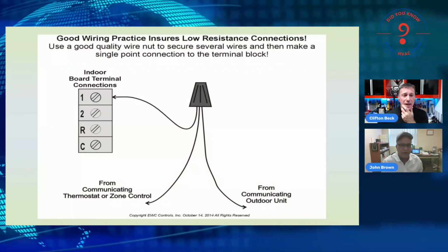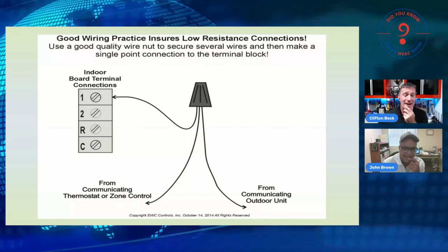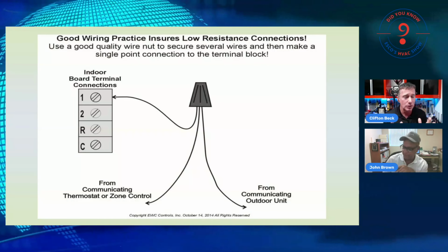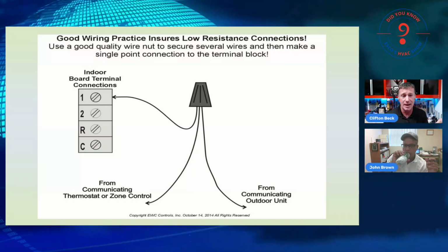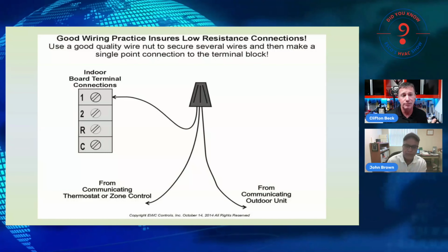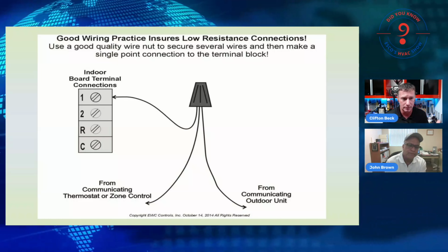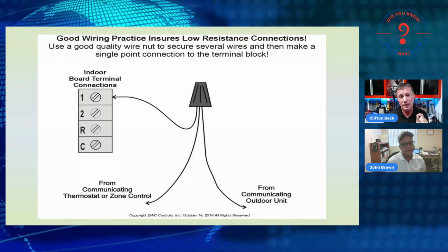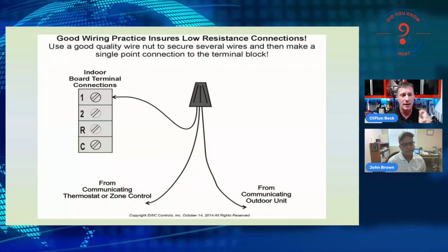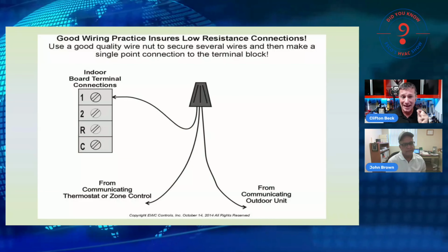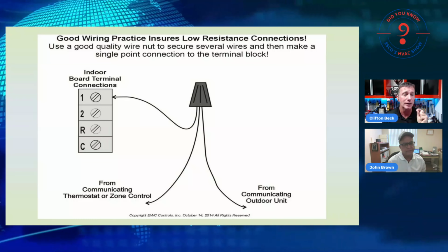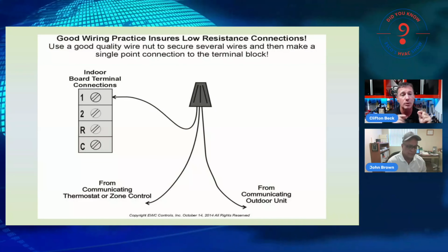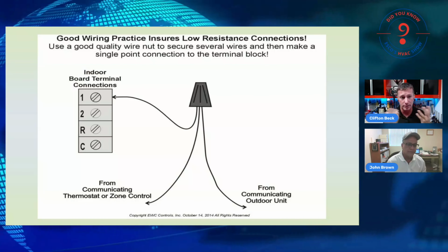So that's very important. It is, John. One of the things that I had encountered with this exact same scenario is many a times with original solid conductor control wire. So we know if the application allows, technicians are going to flush a line set, they're going to reuse the original conductors, and it is acceptable if things are installed properly. One of the things we have to understand is with that solid wire conductor, that it might have passed current through properly on an AC load, because remember, our legacy thermostats had a switch and we were applying a load through that conductor for our thermostat wire.